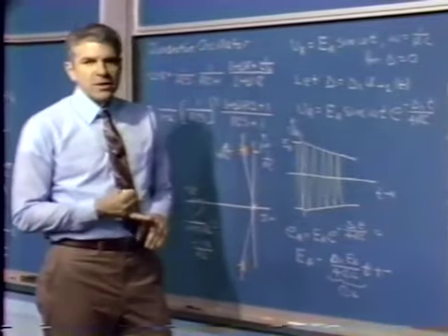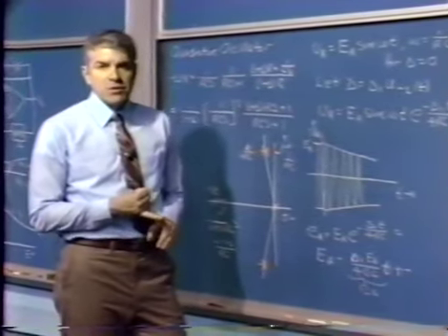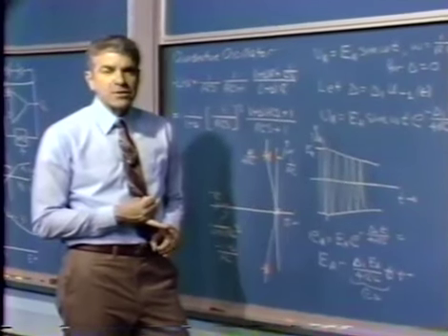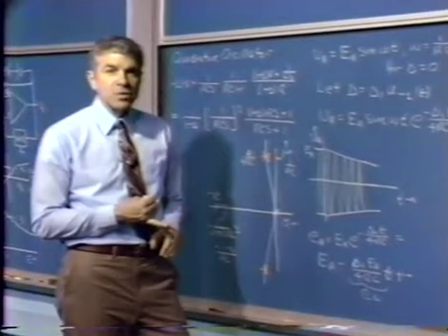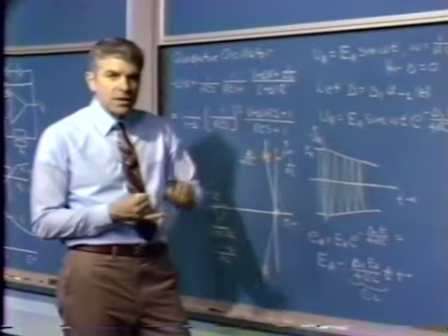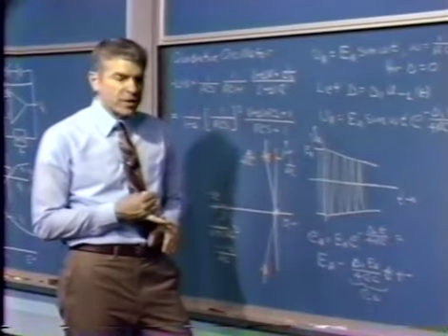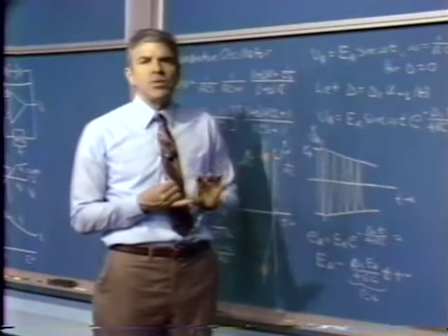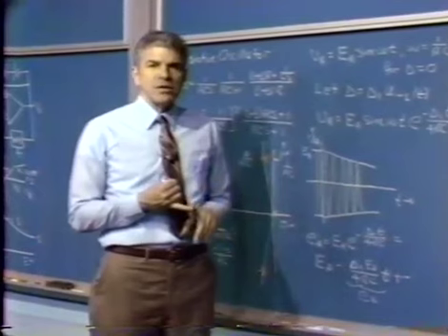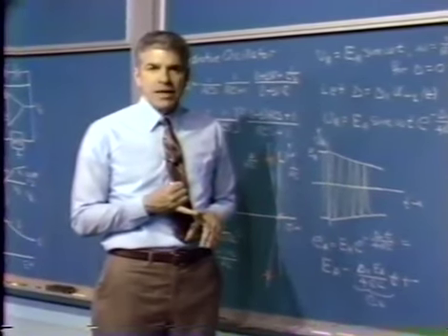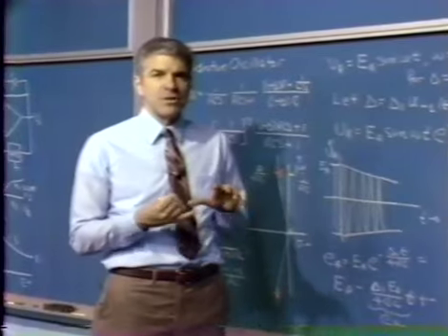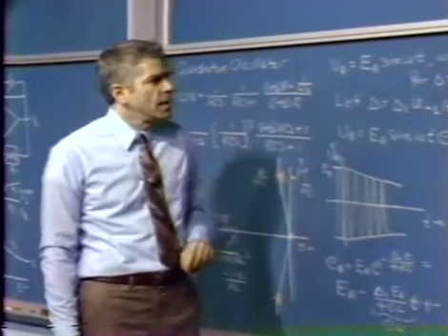Well, let's see. We have a system that we are assuming is linear by virtue of the fact that we've performed a linearized kind of analysis. We're doing an operating point plus a linear change from that operating point sort of analysis. So we have a linear system. We put in a step and we get out a ramp. We conclude that the transfer function that relates output to input for such a system must be simply an integration. When you put a step into an integrator, you get a ramp out.